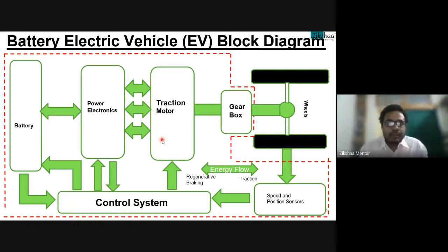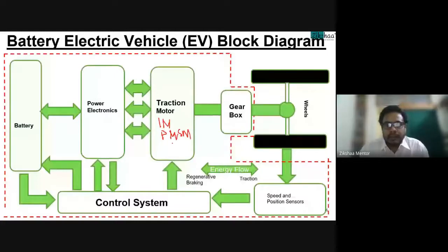Three of the major components of any electric vehicle drivetrain are the traction motors. We have all kinds of traction motors right now in the market, starting from induction motors and permanent magnet motors, and permanent magnet also has BLDC. You might have heard of BLDC, BLAC motors, and also we are looking into synchronous reluctance and switch reluctance motors to reduce the use of permanent magnets.